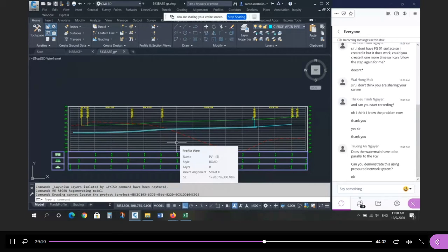So if you change the geometry, you can check the hydraulics. And if you change the hydraulics, you can update the geometry, right? So if you change the slope on the spreadsheet and the pipe size changes, then you have to go and update the size and the slope in the drawing.